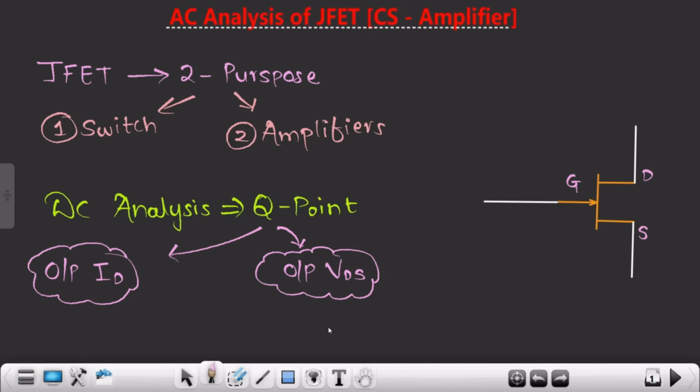Similarly, in the case of JFET we are going to see one modeling technique. I told you that BJT was a current controlled current source, and over here you can clearly see that in the case of JFET we change the input voltage, and thus the current changes. If you remember, ID is equal to IDSS into 1 minus VGS by VP, the whole square. So it is proportional to VGS square. If your input voltage is changing, your ID is also changing. Everything is crystal clear up till here.